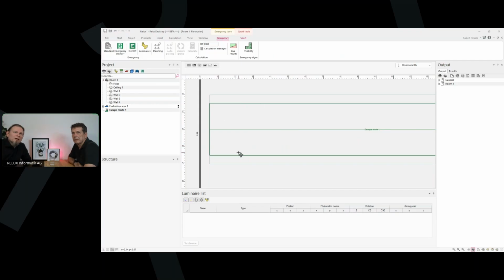And this area has still the same 4 meters width of the escape route, but now we have half a meter of a kind of wall zone, like an offset to the border. So this is also in the standard. In the standard, we now have half a meter from each side, except if it's too small. This was previously a percentage value. This is also built in.